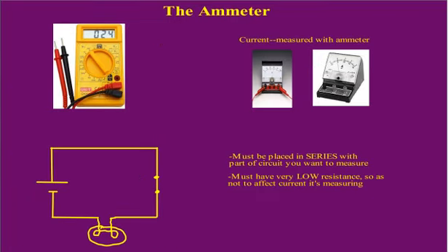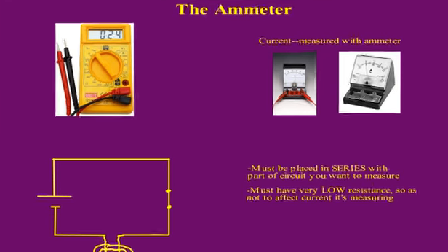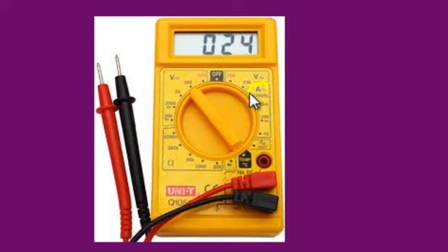We're going to move on to using the multimeter as an ammeter. If you look at the multimeter dial, we're going to have to turn the dial to be over here in the ammeter section, somewhere like that. And we're also going to have to move this red test lead from here to this other red socket. You're going to see that red socket has a label. It's a little obscured here, but it has a label with an A, for amps.